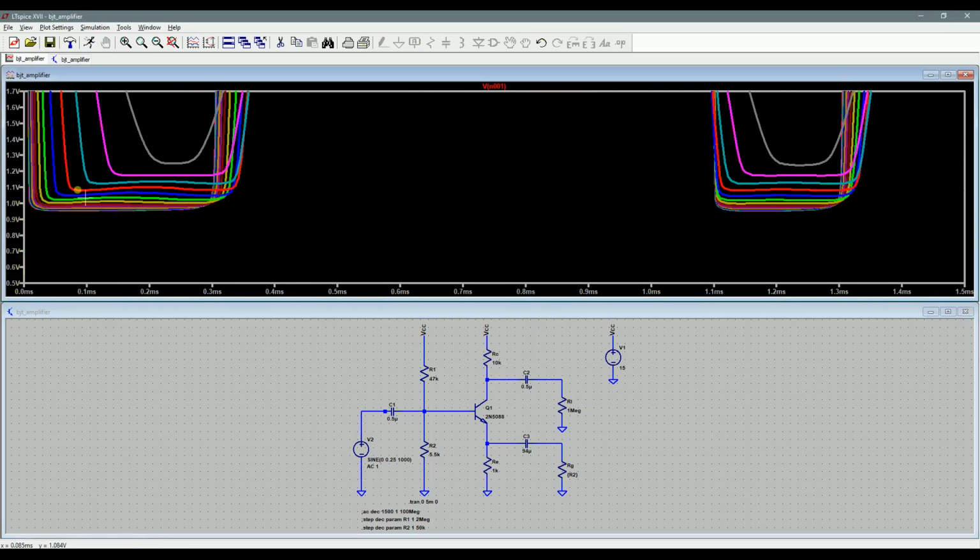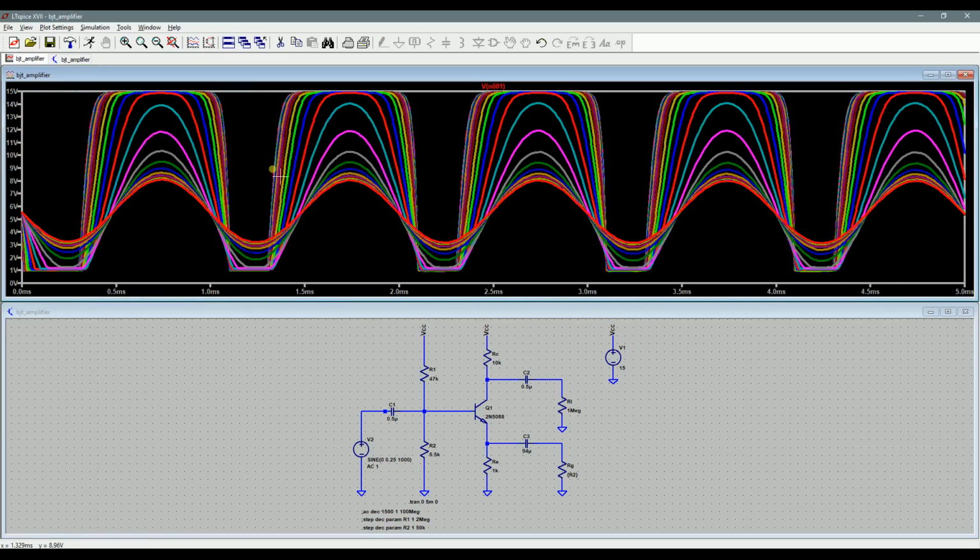But essentially, what is happening here is for the transistor to be in the active region, the voltage in the collector must be at least around 0.2 volts greater than the voltage in the emitter. When we have these big gain values, we're getting down to a place where we're no longer going to be in that region. So when it's trying, oh, I got to go down here, but then it's actually not amplifying anymore. It's not acting in the active region, so we don't see that value reflected in the output.